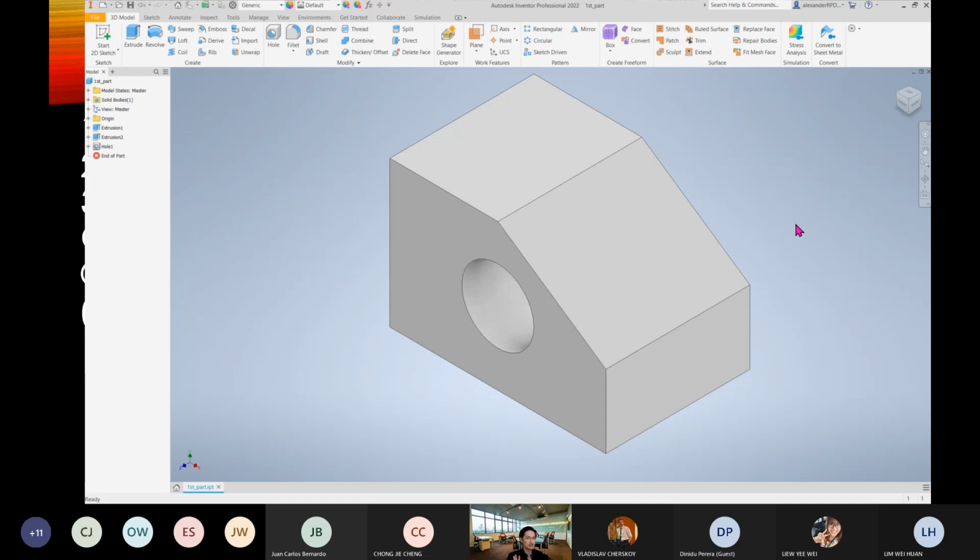But I just want to share with all of you, you look at your design tree right now. When you do collaboration, people read your model. It will be very clear when they want to modify. For example, your boss tells you that you cannot drill 0.5 or 1 inch over here, we change it. Then people look at it and say, okay, change this one. Right click, edit features.